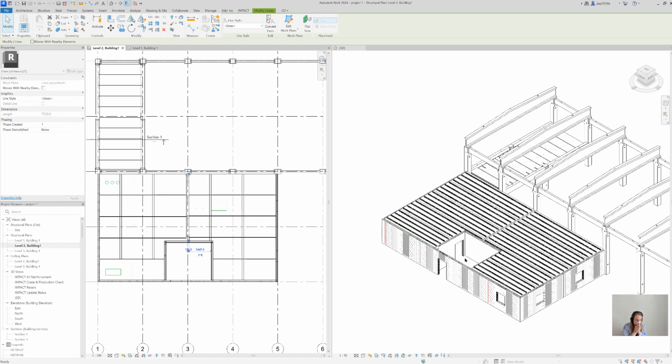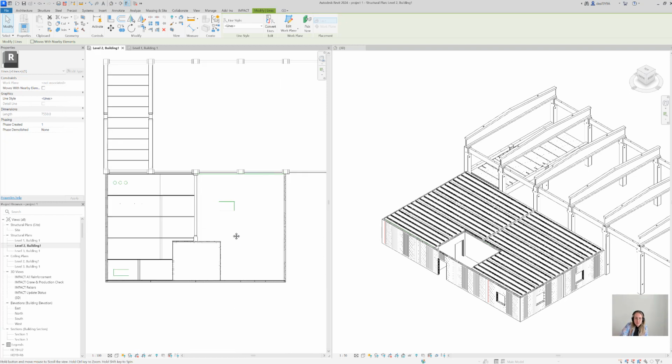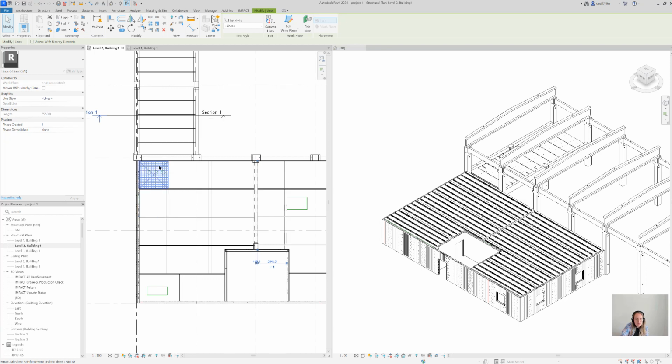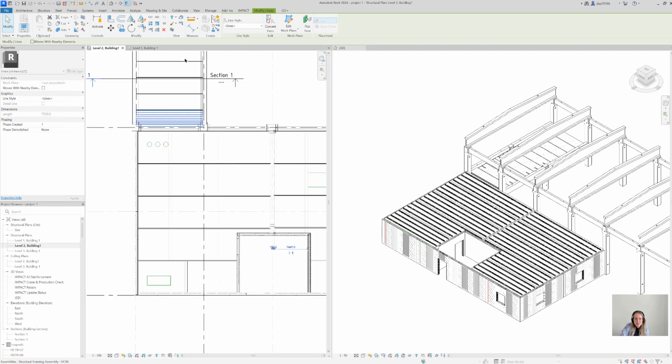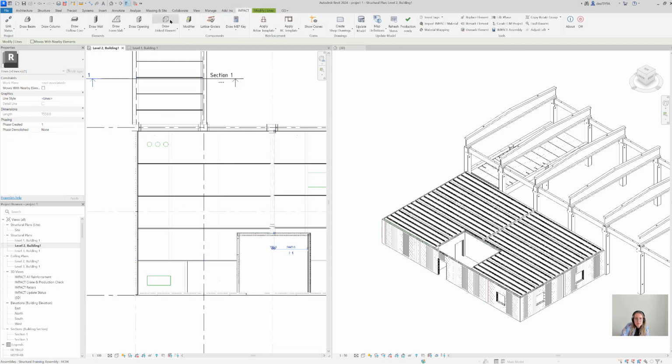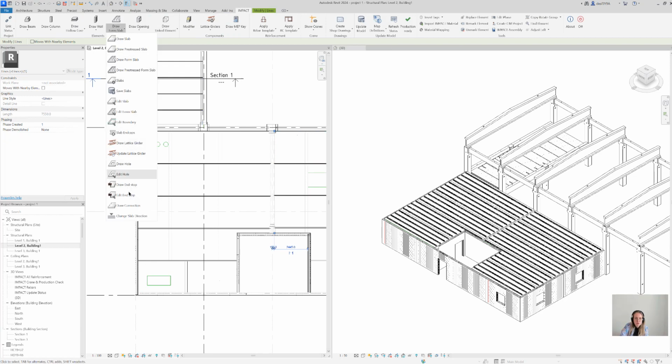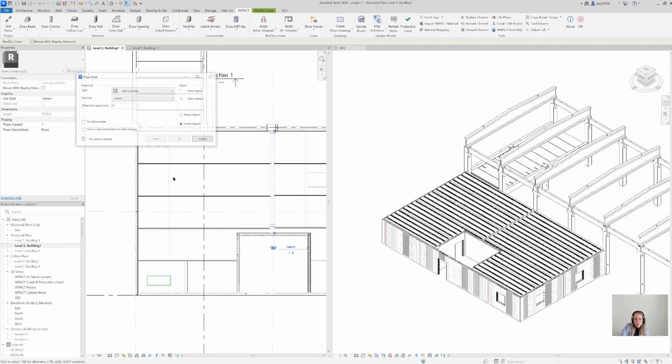Now we have the foam slabs, and what we need to do now is draw some holes and recesses, and here I have some model lines that we can use. I'm going to demonstrate different ways of drawing recesses. If you go into the foam slab, in the following menu you can say draw hole.